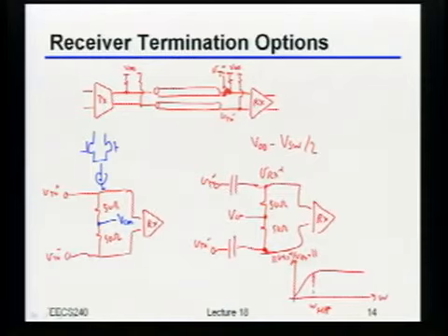So for example, if you've ever heard of 8B/10B, 8-bit 10-bit, basically you add an extra 2 bits onto what you're transmitting. That has the property that it forces things to be DC balanced over 10 bits. There are other codes, for example 64/66, which is a similar idea. They added an extra 2 bits to try and make things DC balanced over 66 bits. The trade-off being that obviously if you have 8B/10B, you have a 20% overhead and you're sending these code bits that don't actually do anything useful.